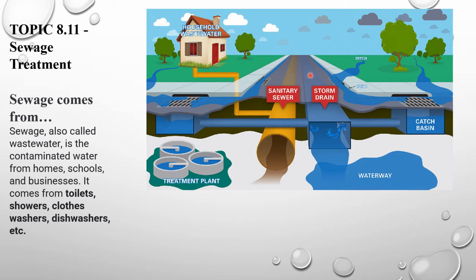And as you can see, the sewer line and the storm drain line run under our roads, and then they go to the wastewater treatment plant sometimes, and other times the storm drains and the storm lines will go right into a stormwater management facility before it gets released into a stream, or it goes directly to a stream and gets released right from your street and the storm drain right into the water. Now, if they don't work together, then the sanitary sewer is just going to go to a treatment plant, which is what we're going to get to next, a sewage or wastewater treatment plant.